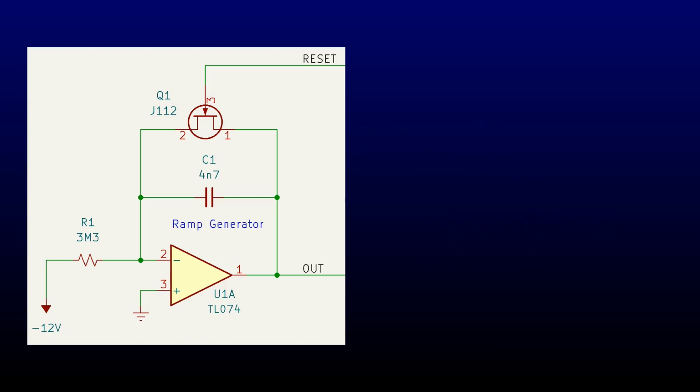The switch I'm using is a JFET. I'm not planning to cover those in detail for a while. I'll just give you a cookbook approach for including one in an integrator. First off, the voltage at the source and drain of the JFET must be above ground. You can get away with as much as a diode drop below, but it's poor practice to push things. Here, the source terminal is at virtual ground, and the drain is positive because we're integrating a negative voltage, so there should be no worries.